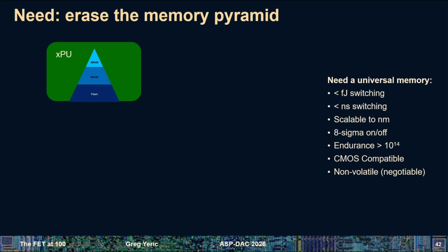And then also the error is typically just the threshold voltage of the device after you program it isn't where you want it. So there are these really complex programming algorithms to say, I'm going to program a 1, check it, didn't quite get there, so I'm going to push it a little bit harder. So there's a lot of stuff under the hood in this really cheap flash memory that you buy.